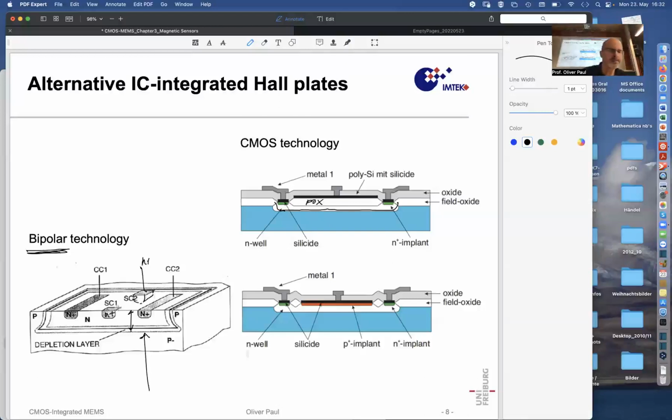So schematically shown here, this is all deep, and so these are then the contacts through which current flows into this N layer and out of it again, and then you have these two devices. And again, this figure shows that it's an old schematic, because nowadays, with this idea of current switching, nobody would draw a device that is not symmetric.